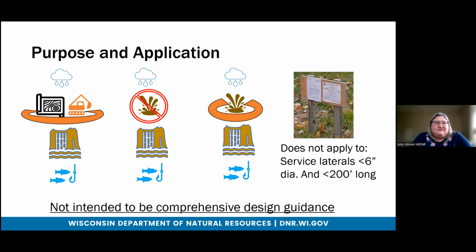So there's erosion sediment control, and then there's 2 ways that we prevent drilling fluid from getting moved into the waterways via runoff. One is to reduce the risk of having an inadvertent return in the first place. And the second is to have a good plan to contain it quickly when we cannot prevent it.